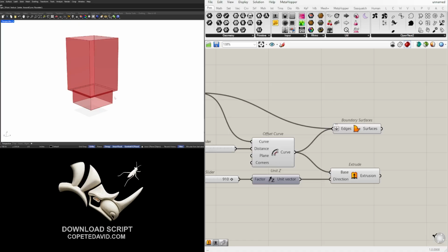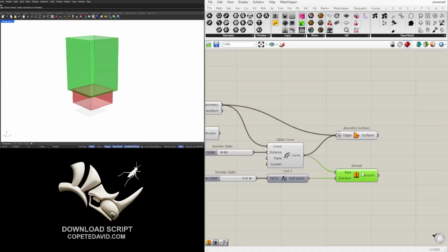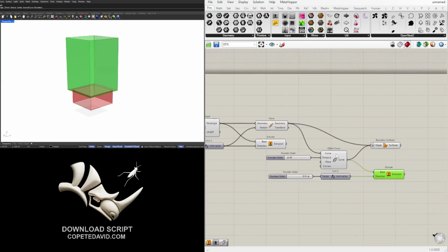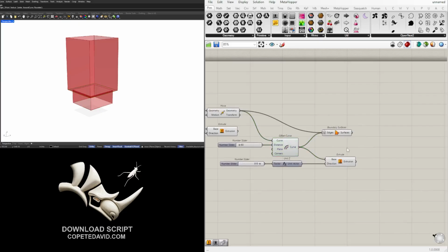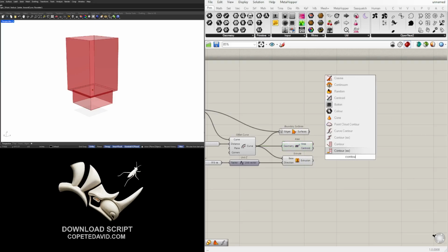Now for this design, we're going to be doing it in a simple way. What I mean is we're going to be creating where the floors are. We're not going to focus on the interior design. The floors are just going to be there to show you where we can anchor the facade onto the floors. So we'll go back here to this component, this offset, and we're going to bring the midpoint by using an area component. And then we're going to be creating contours.